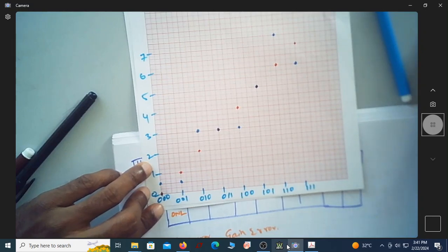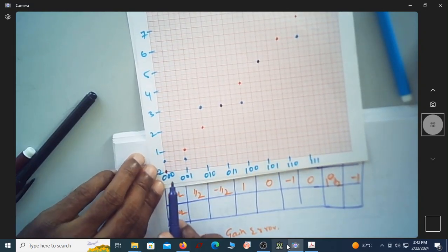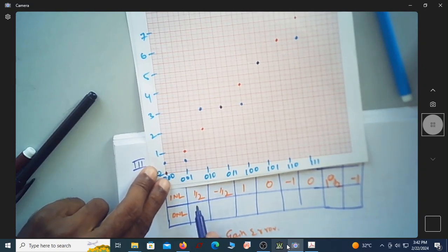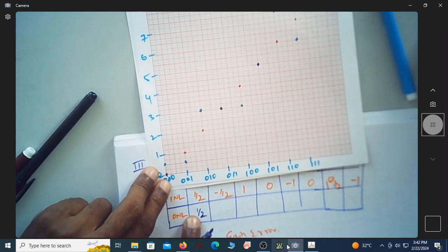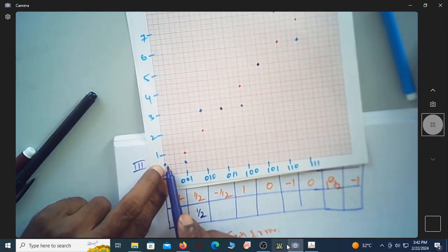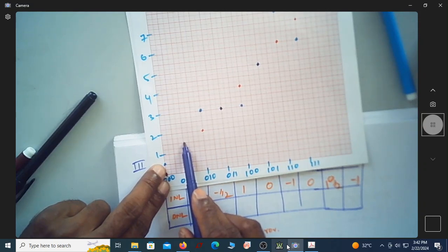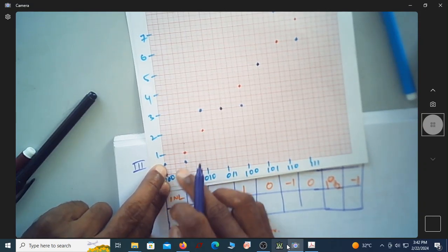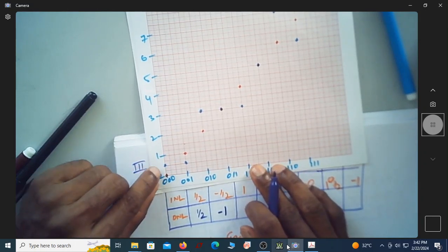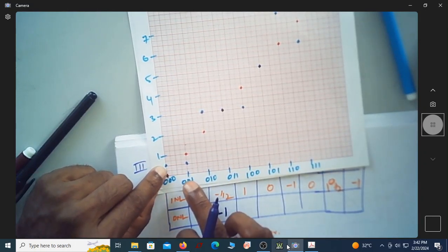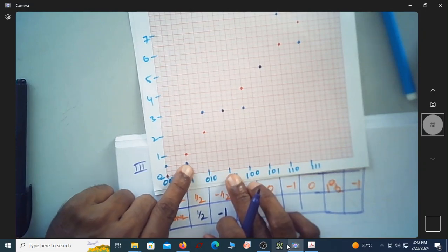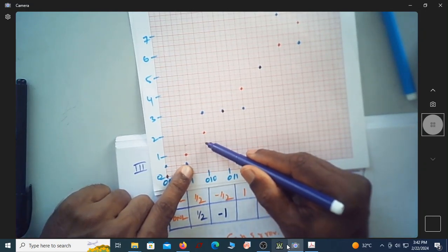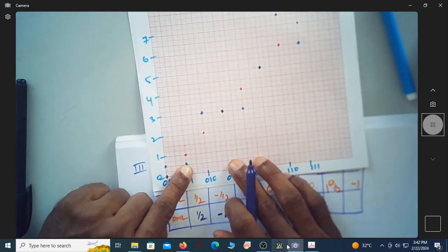And then can we find what is DNL now? So DNL, it is initially half now, because whatever is your INL, that will be DNL initially. Then from this would have been here, this would have been here, but it's actually here. So this is minus 1 LSB. See, this is your bit. When the increment of 1 bit happens at the input, output would have been here, but it is still here, so it is minus 1 LSB. So taking this as reference, this would have been here, but it is actually here. So how much is above here?